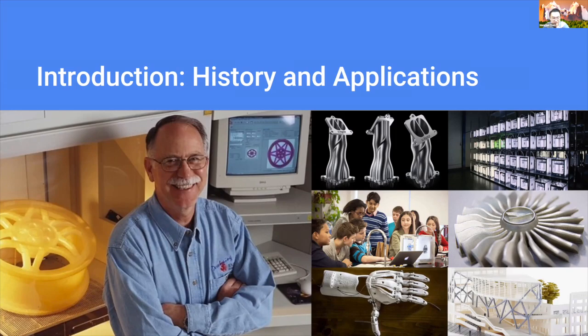So, as I mentioned, injection molding is more expensive and sometimes time consuming. Subtractive manufacturing, like CNC machining and laser cutting, has its geometric limitations. So, for instance, if you want to prototype a product and you want to tweak it on a very continuous basis to fit the application, it's very difficult. It's very expensive and time consuming to, let's say, make injection molds for each of the iterations. What you can do is use a 3D printer. You can continuously tweak your designs on the computer.